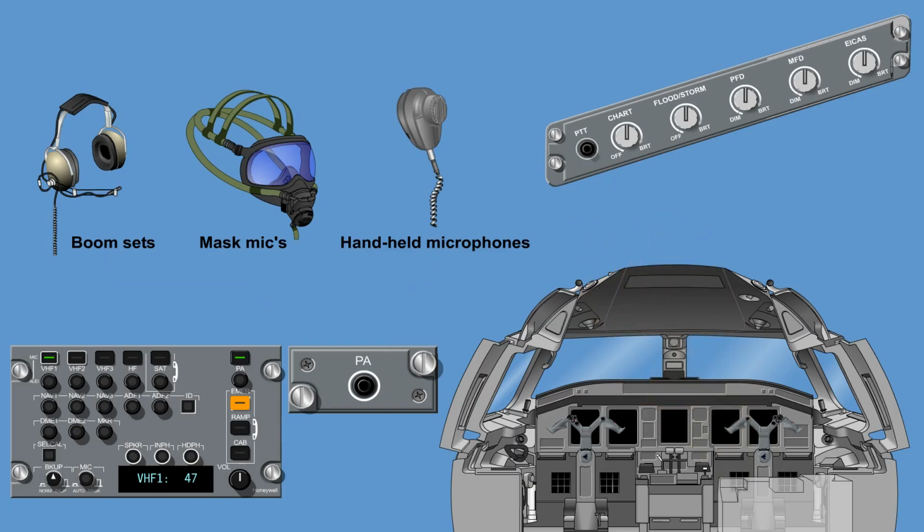If another audio panel is talking on the PA, the display shows busy. To terminate the call, the PA microphone selection button is pushed again. The light extinguishes, and the display defaults back to the last active radio.